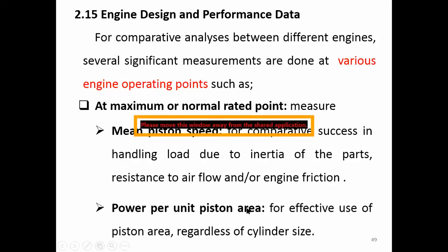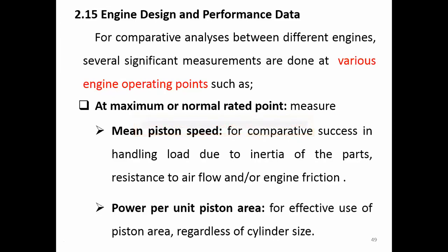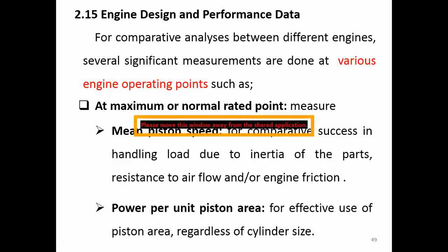area at this condition, because we want to look at the effective use of the piston area, right? The piston that we design has this frontal area or top surface area. How much power can be delivered or come out from this area of the piston, regardless of the engine cylinder size? Cylinder size means the volume of the cylinder. With different volumes of the cylinder, we can have the same bore of the cylinder. That means the same piston diameters.